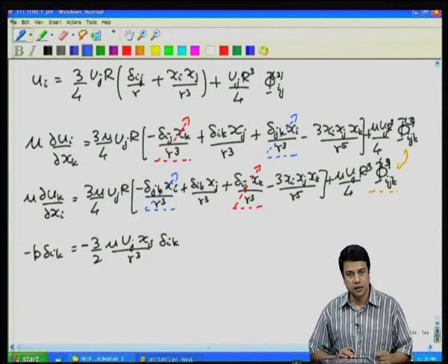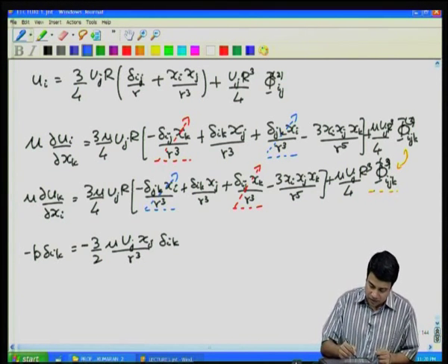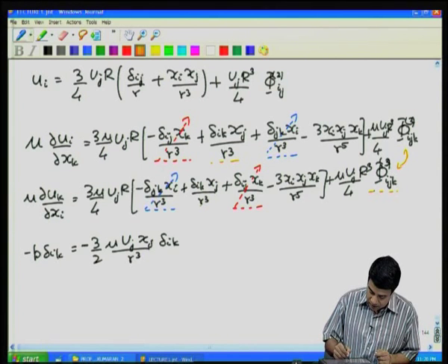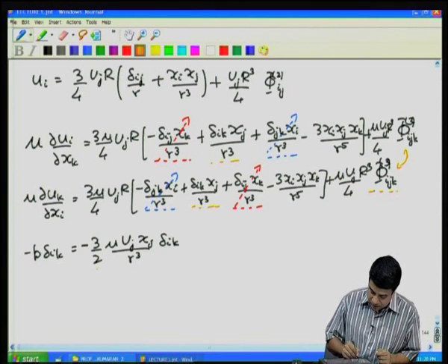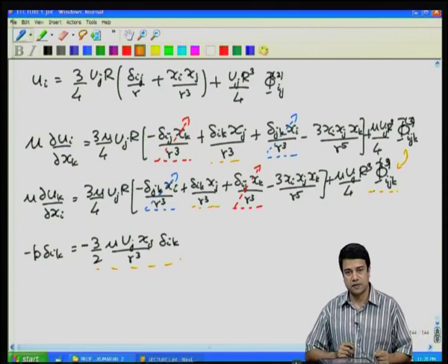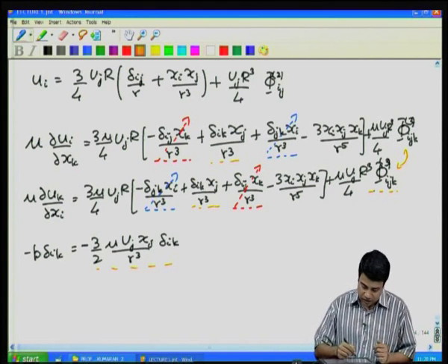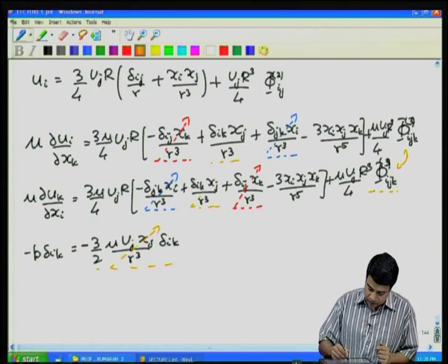That leaves me with a term in the middle in all of these cases. Those appear with a positive sign in the expressions for the velocity gradient, but you can see that an identical term to these is appearing with a negative sign in the expression for the pressure. So, when I add up the pressure to these two velocity gradients, these terms will all cancel out.